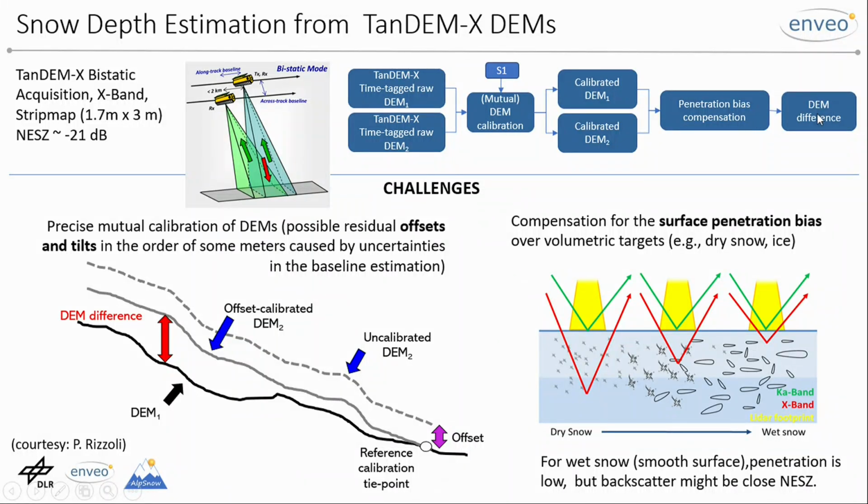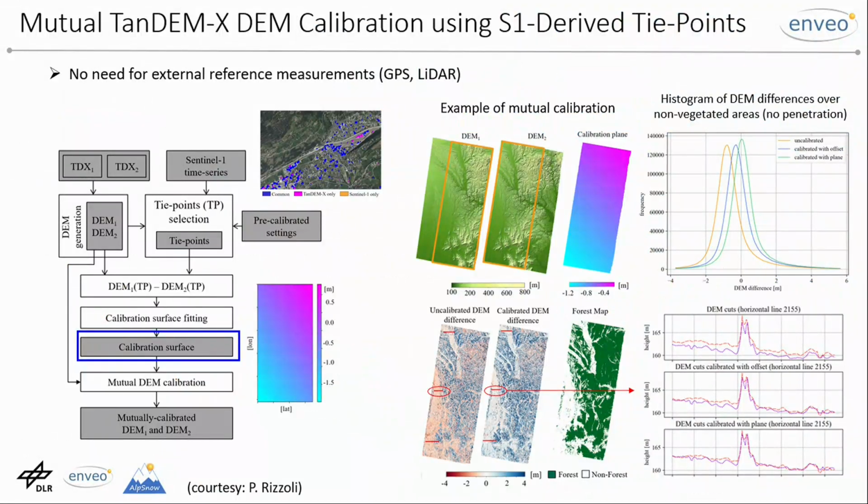And we can apply the DEM, and you see how this looks. A couple of people tried this with standard TanDEM-X data, and the outcome was, no, it's not suitable. You need a better processing, and actually together with DLR, we developed a procedure which combines permanent scatterers, stable points of Sentinel-1, in order to correct the orbits and the phase plane of TanDEM-X. So to remove the baseline error which is present in the data, and this is shown in this graph.